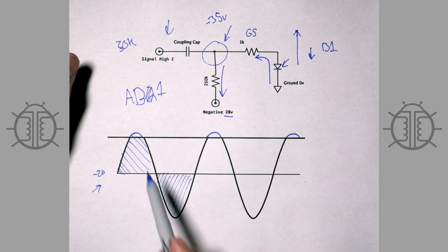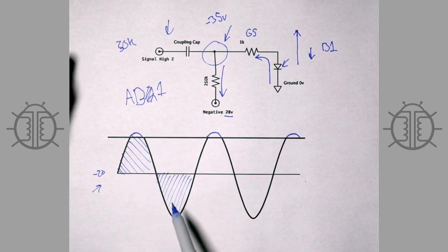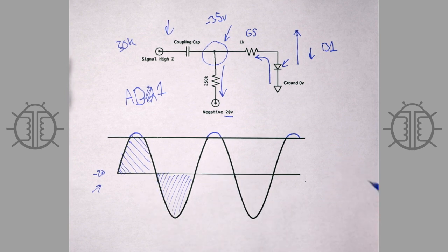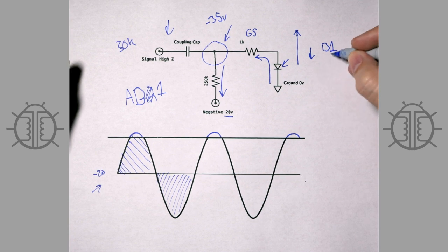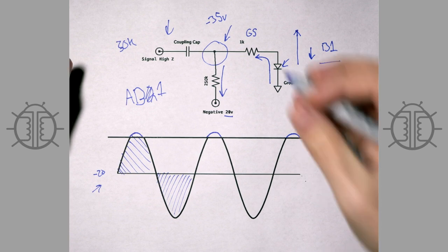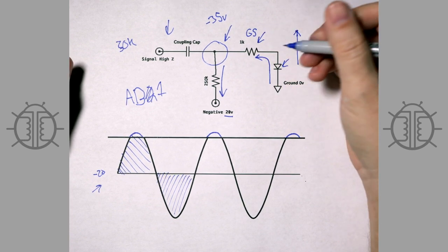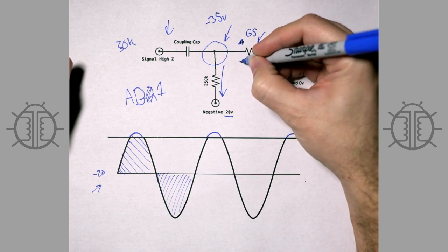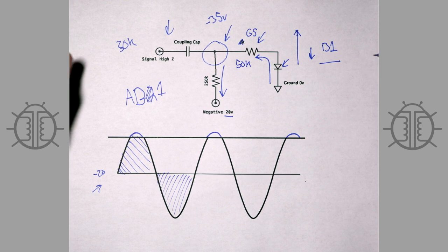And as we looked at before, if you're clipping, at least momentarily, you're creating a little bit of a negative half-wave rectifier situation that will briefly lower the bias of your output tube, but the recovery will be very quick, and that's the main thing, so that's also a good option. Another thing that people do is they take the value of this grid stopper and make it very large, so they may make it 50K or something like that, and that's fine.